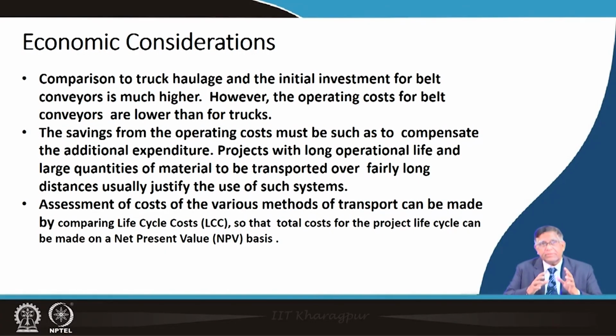That is why, when you make the economic considerations for whether you will go for an in-pit crusher or not, you will have to develop the economic model. And the economics is not seen only by the operational thing, you will have to have technical feasibility. Technical feasibility may be all right, but if the rock is so sticky, then when you are using the conveyor belt under those conditions it may require more maintenance. Though its operation cost may be less, you cannot meet the production, and at that time also it will be economically not viable.